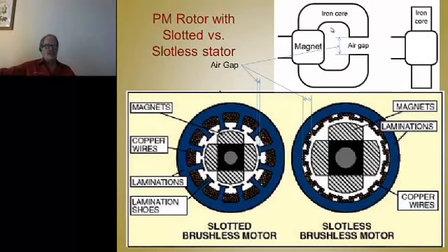So we're cutting this thing apart here with a hacksaw, and we're going to stick a magnet in there. So you got a north pole there and a south pole there. So we got flux flowing around here like this, you see. And it jumped across this air gap, you see, and we're defining the air gap. So now let's conceptually turn the elements or the components of that circuit into a couple electric machines.